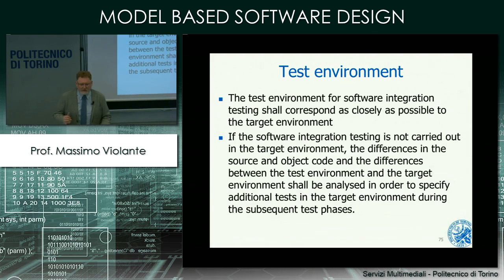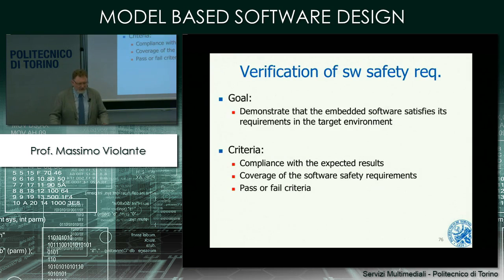Once the test has been completed, so we are confident that what we integrated is what we specified, we have to do the verification of software safety requirement. So we have to demonstrate that the embedded software satisfies the requirements in the target environment.